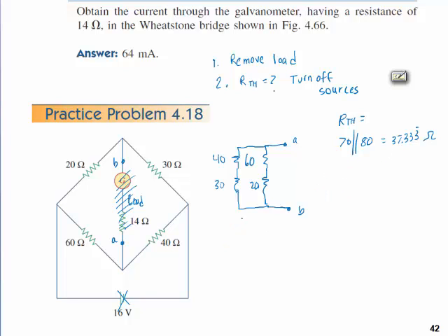How do you find V Thevenin? V Thevenin means put the source back in. I think this is going to beep when I erase, sorry about that, those beepings. I'm on a different computer today, and it seems to work different. My pen seems to work different with this lower version of PowerPoint. So it says put the source back in and measure the voltage between terminals A and B, with the load not in.